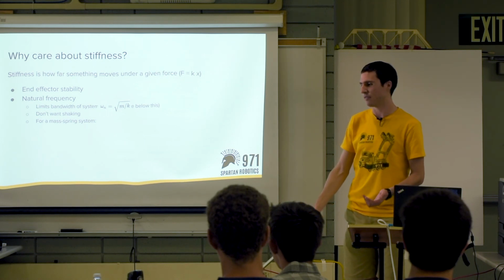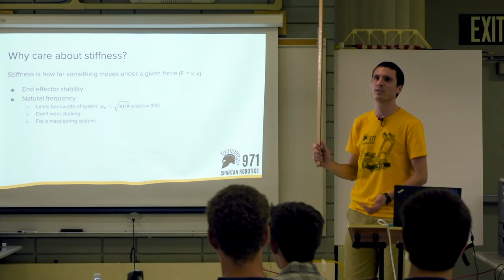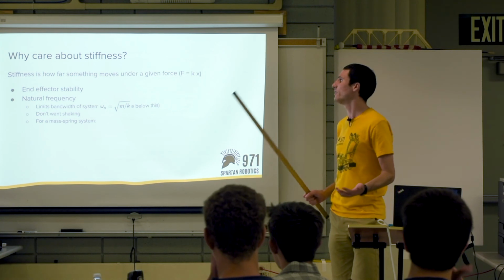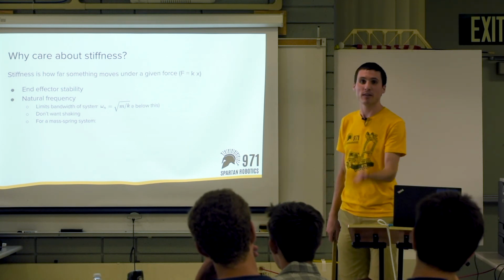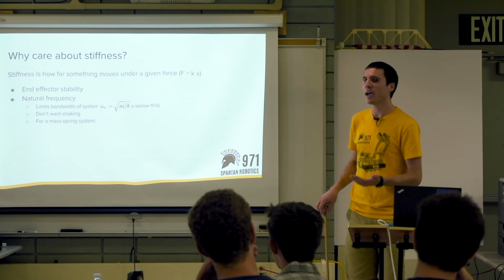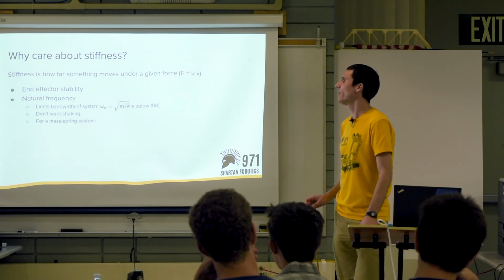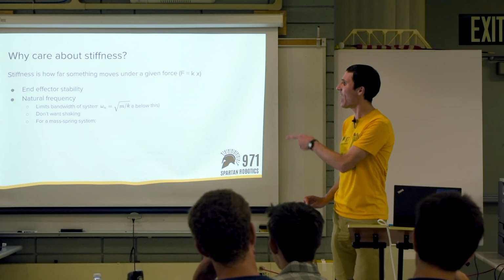That's not good. So what we have to do is go into software and tune it down so it raises up slowly enough that it doesn't vibrate. We picked a ratio that's going to be able to lift our arm quickly, but if we're not careful, we can't actually do that. This is actually something that happened to us.